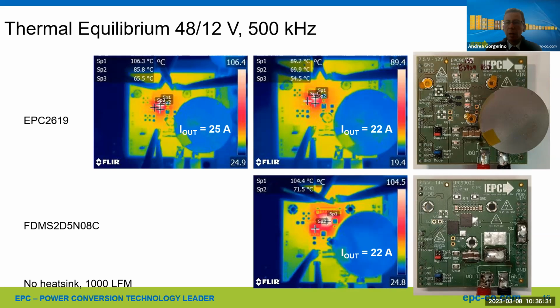And that loop is really what creates all the ringing that you see in the switching waveforms, the overshoot at the turnoff. Those are major contributors to EMI, and you can greatly reduce them by using GaN devices and optimized layout with GaN devices. So yes, you can also have very effective EMI designs with GaN, and we have many customers that are in production today with GaN devices at quite high switching frequencies.